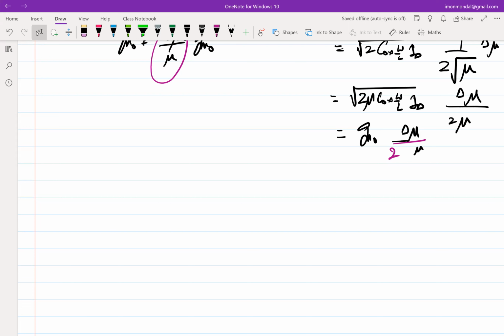Right. So in a transistor, I can push a current into the drain of the transistor. I can pull current out of the source of a transistor. So essentially, there are two ways of feeding current, and there are also two ways of developing VGS. Right? I can either change the gate voltage, or I can change the source voltage. So essentially, there are two ways of feeding current and two ways of developing VGS.